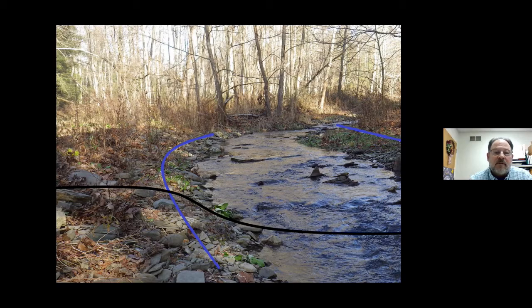This is where we'll start seeing some finer deposition of sediments, or this is where the debris ends up collecting. Those are some of the indications. Vegetation can sometimes be an indicator of where bank full might be, although in our areas it's kind of tough to determine by vegetation. We're basically looking for that floodplain deposition area on tops of point bars or these floodplain areas here throughout this section.